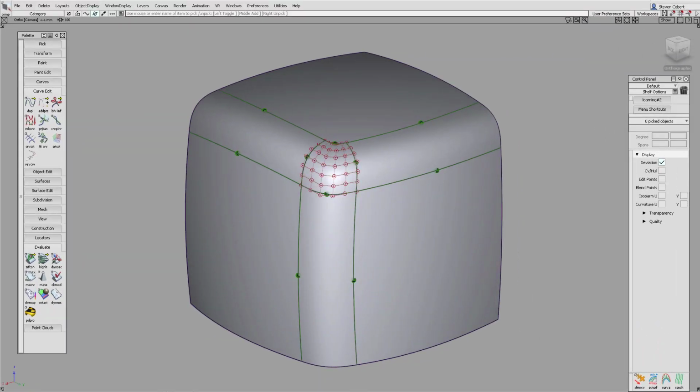We're now going to look at a method for creating corner fillets. The same principles can be used to create any corner, whether we have G1, G2 or G3 fillets. But in this case we've got 3 G2 fillets of roughly equal size coming together. For A-class work, a triangular corner surface would not be acceptable, so we have to create a 4-sided corner surface.